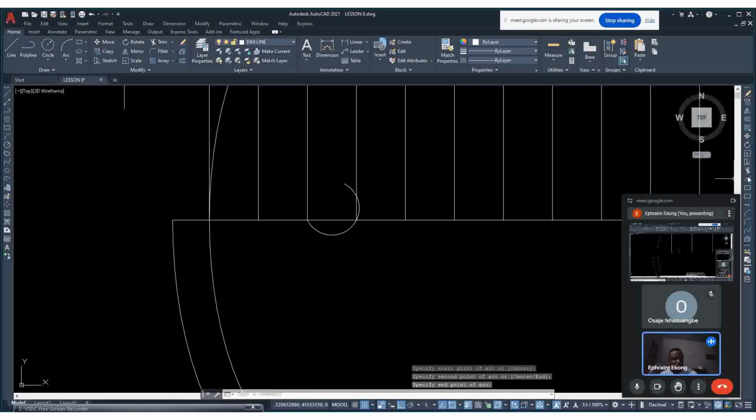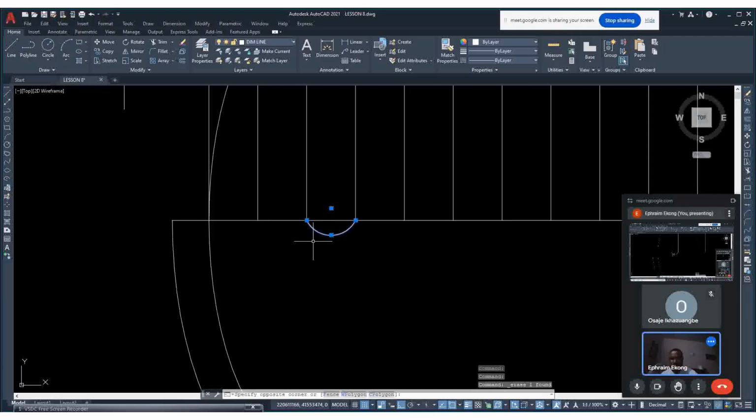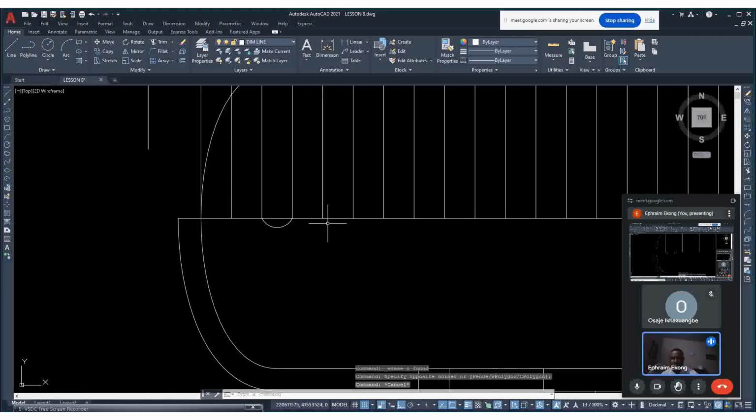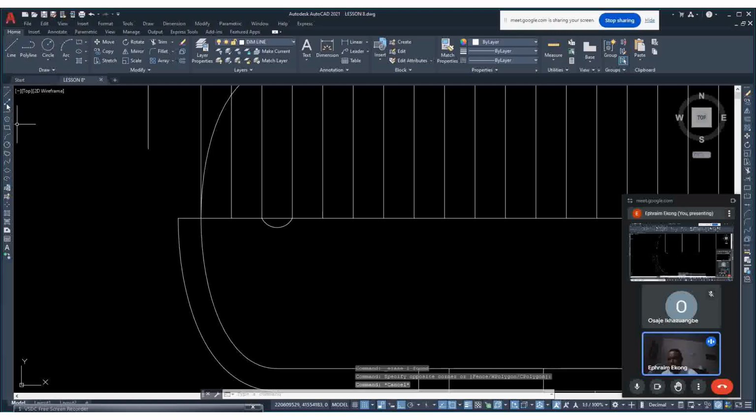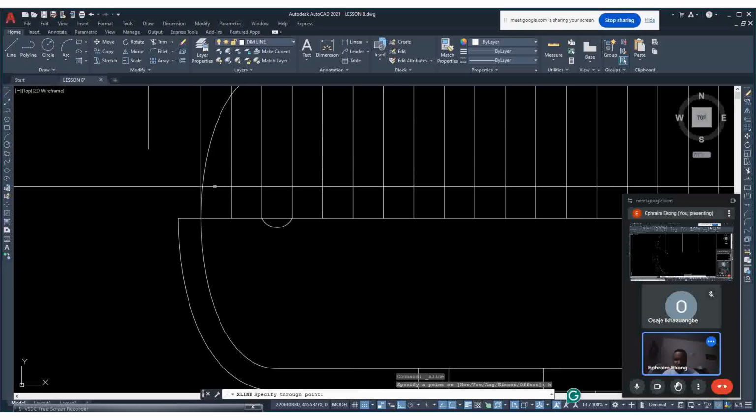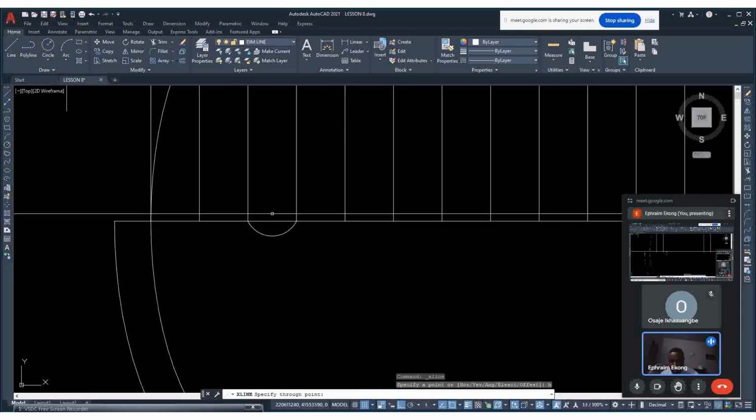After that, go to trim. Click on trim and press enter. Then trim. You highlight this and press the erase key. Okay. So what next again? This curve has something like up, here. So go to X line, type H and press your enter. The H means horizontal.